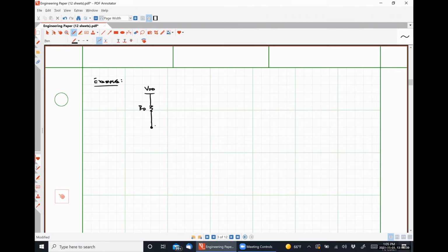So here we have some resistance RD. Here's V out. Here's our terminal where we apply our input voltage. And let's say that we have RG here and some biasing voltage VG here, right? So this is our amplifier where we are assuming that this guy is biased in such a way that it's operating in a saturation region and all that kind of good stuff. We're going to analyze this guy with CLM and body effects ignored, just to make the math slightly less of a pain.